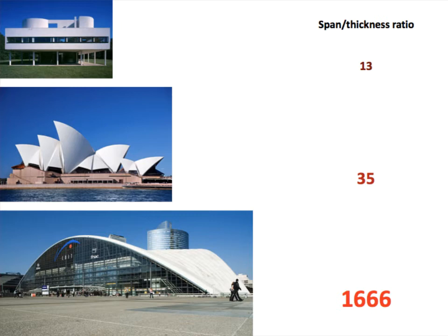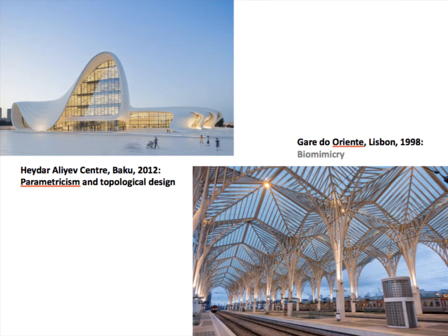For buildings of more modest scale, a much simpler structure normally provides the best compromise and lowest carbon footprint, even if it is less efficient in its use of material. The inefficient structure of the Villa Savoye was entirely appropriate for the spans involved, due to its simplicity. In contrast, the organically based or free-flowing forms, shown here, are mostly inappropriate. Their engaging forms are overly complex for their scale and not related to their physical function.